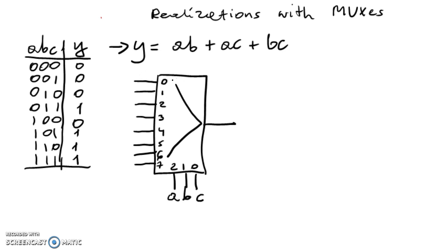And then from the principle of operation of the multiplexer, you know that if you put 0, 0, 0, which is the first row of the table, you simply select this input, and this input's value is transferred to the output, Y. The value should be 0, as stated in this table, so you must put 0 to be transferred to Y. By changing to the next value, 001, you simply read the value from the table and put 0 here also.